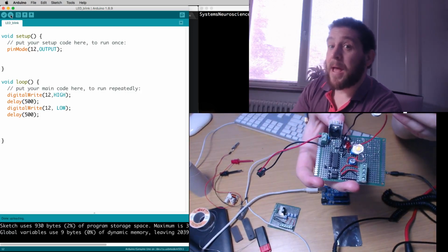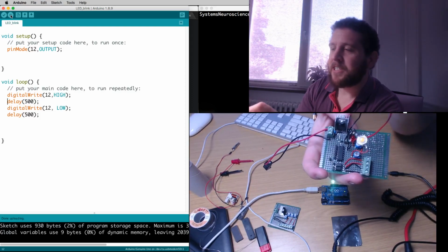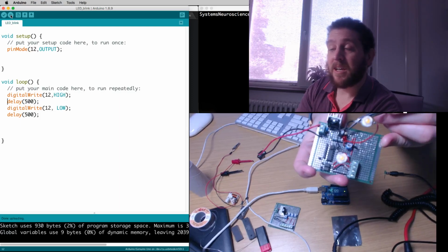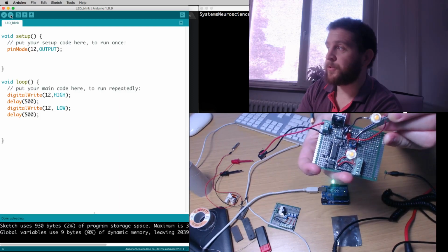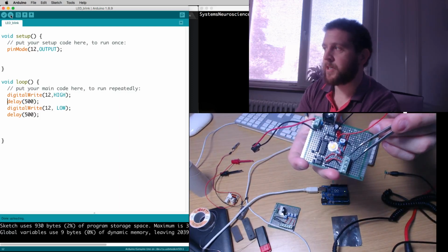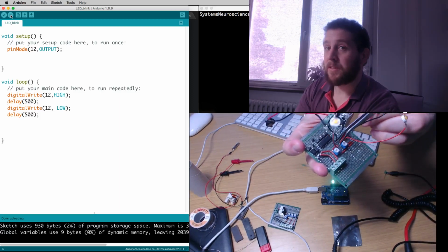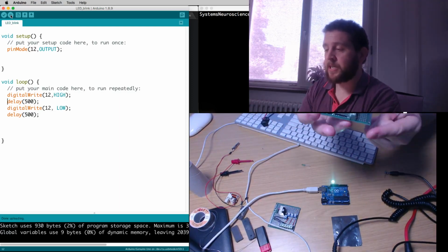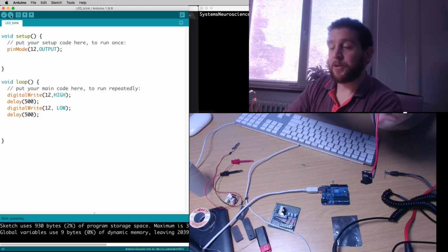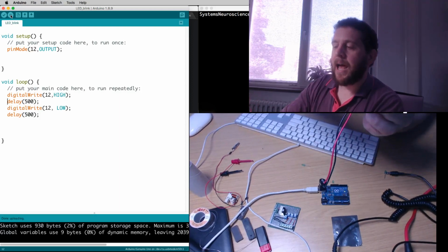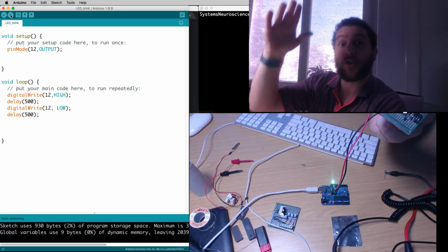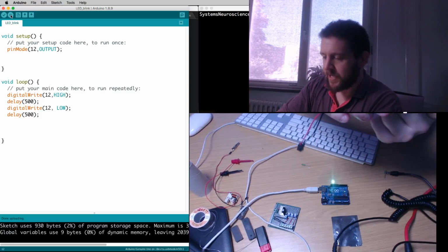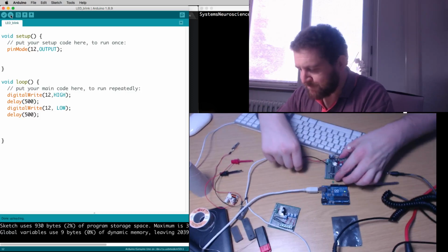Now, where is the power coming from to drive these ultra bright LEDs? Well, that's coming from the 9 volt power supply here. Okay, and I've got it coming through 2 resistors. So here I've got some resistors, one resistor here and another resistor here, these 2 blue and white things. Okay, so essentially instead of coming straight out of the Arduino now, I'm going to connect the Arduino to this transistor switch, okay? And then that transistor switch will then switch the higher voltage, higher current power supply from this 9 volt regulator. Hopefully that should still be clear to you.